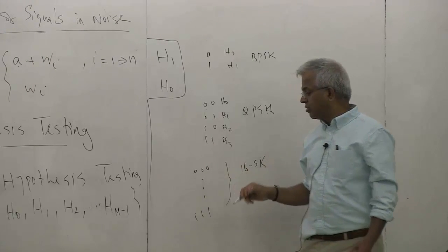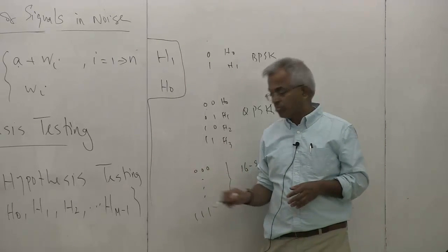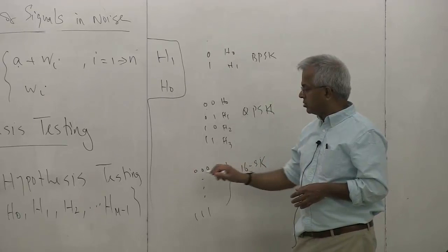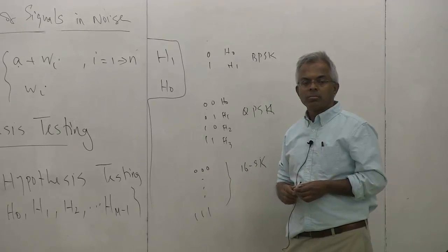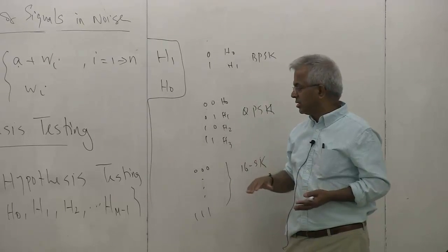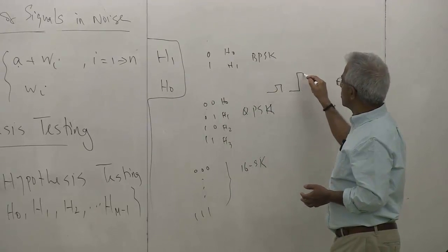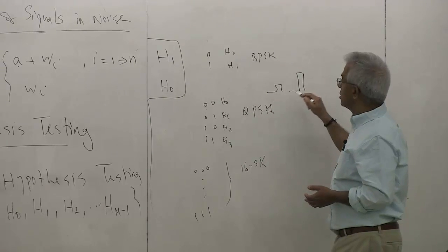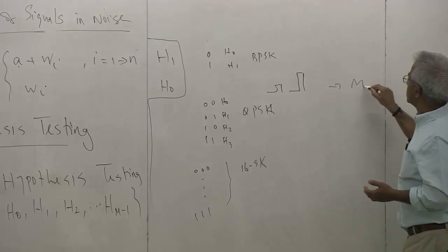You can use frequency shift keying or phase shift keying or PSK, lots of modulations to transmit. Or PAM, what is it? Pulse amplitude modulation, right? So you may use a signal like this, the other one may be like that. That's pulse amplitude modulation. But by the time it comes out, you may see something like this.